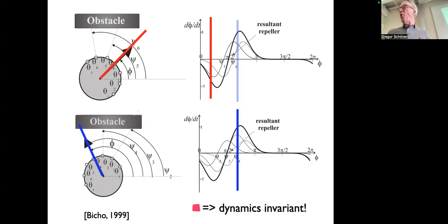And there you can program a low-level robot, and it essentially has distance sensors like that. And what a lot of people do when they first think about it, right? They have, let's say, 2 sensors, one to the right, one to the left. If they sense something that's closer than a certain threshold on the right, then I should turn left.